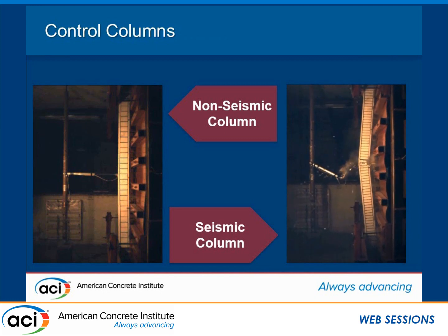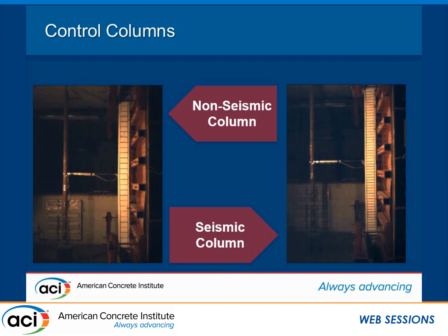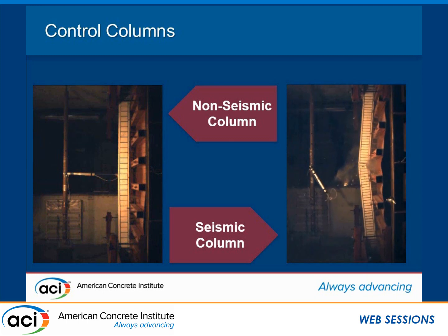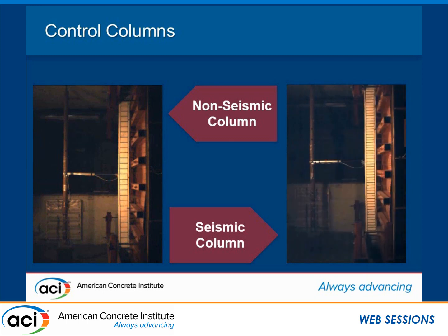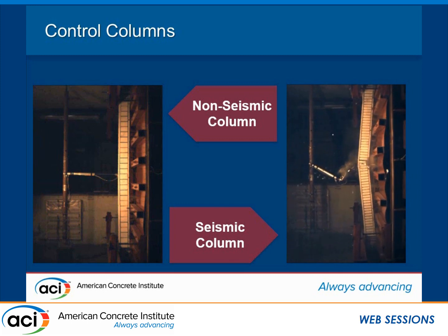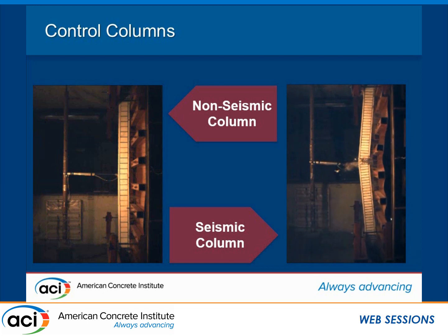Okay, well, the difference between the two, there's a couple pictures on the next page, so we'll see this, but both of them had heavy damage at around midspan. These columns were intended to provide some degree of rotational restraint at the ends, but it wasn't fully fixed, so in actuality, the higher moment region would be in the middle of these columns rather than at the support locations.